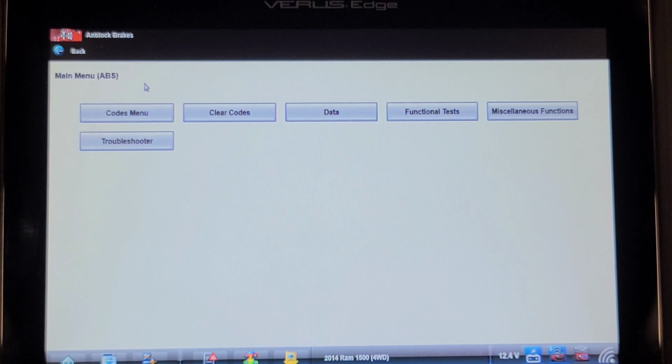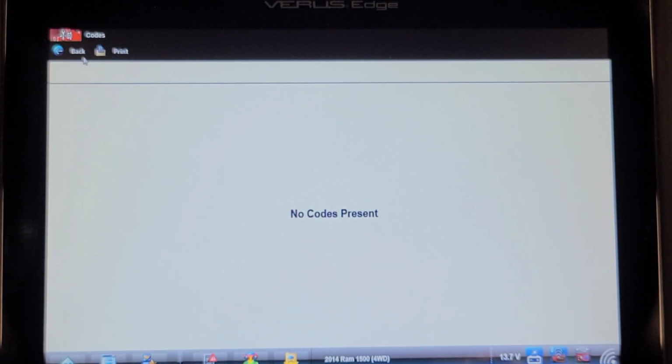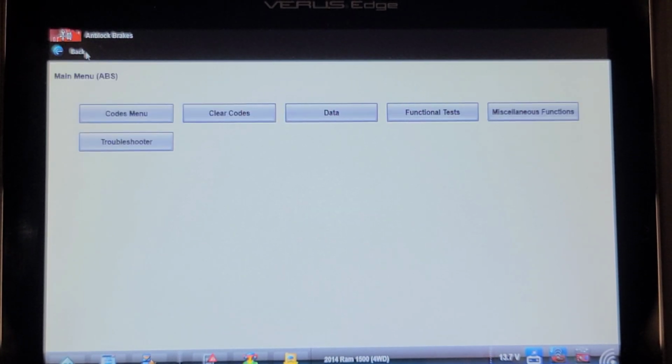Okay, I'm going to try and operate the power steering with it not running and see what it does. Because this is electric power steering. Oh, there's no assist. There's no assist unless it's running. Well, there it goes with its hocus pocus again. Checking for codes again. No codes, yet the steering wheel is wobbling back and forth like it was before.